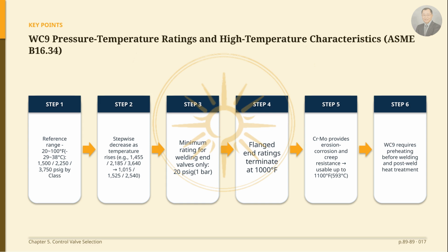Chromium and molybdenum provide erosion corrosion and creep resistance, allowing use up to 1100 degrees Fahrenheit, or 593 degrees Celsius. However, WC9 requires preheating before welding and heat treatment after welding.